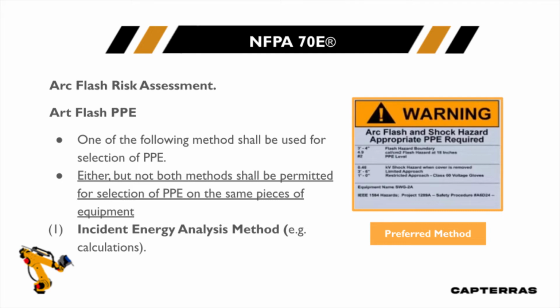In other words, if we look at the ATPV value of PPE, if we look at the clearing time of the breakers, the age of that, all those things, I want people to think about what they're wearing for their PPE, not just put stuff on without thinking about it.